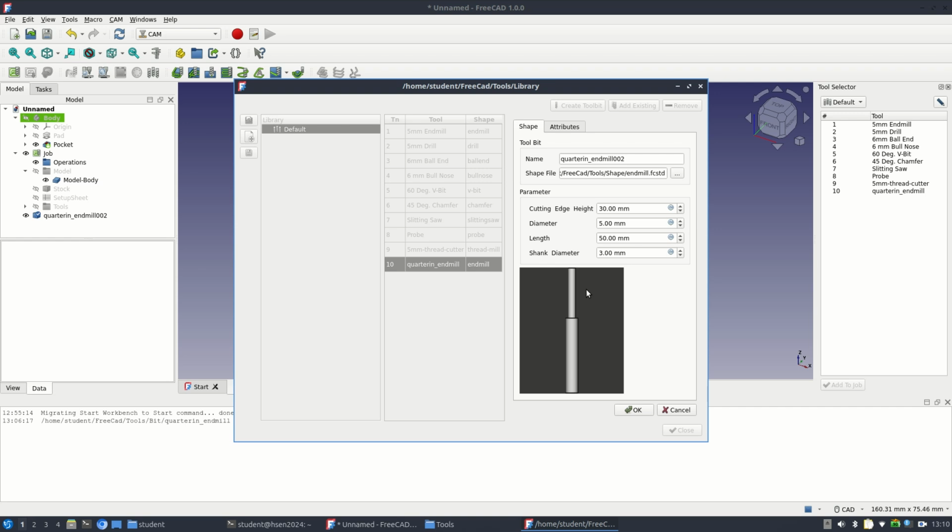It could be as easy as starting over the process, deleting and getting a new FreeCAD downloaded. But I click it here and I got this window. So the thing that we're mostly worried about here is actually the diameter of our tool bit, because that's gonna have a direct impact on how the G code is going to be created.